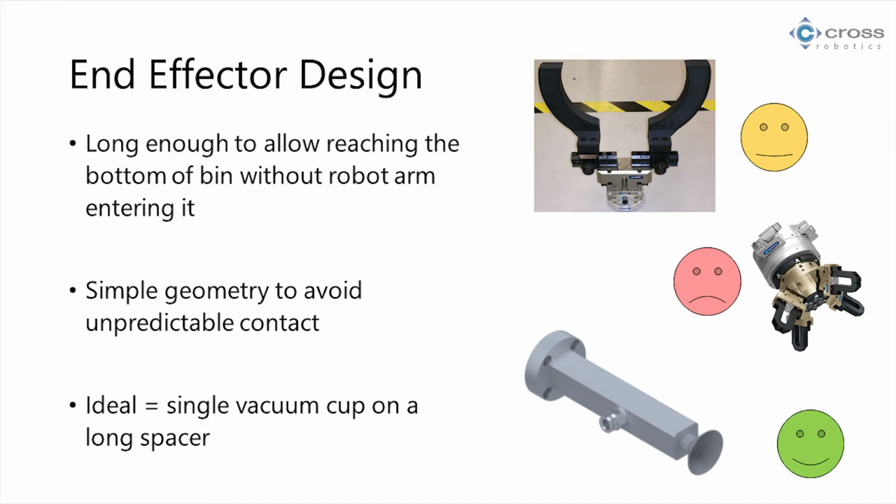So this end effector is complicated, right? You can teach it. So you can upload a CAD model of your end effector and the software will figure out how to approach your part so that the end effector doesn't collide. But the more complicated your end effector, the more time that calculation is going to take, right? So you can expect your cycle time to go up if you have a crazy end effector.